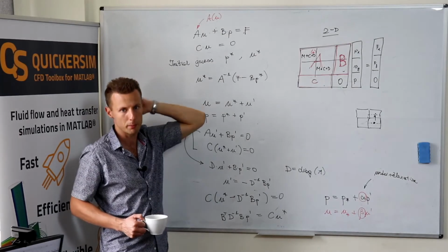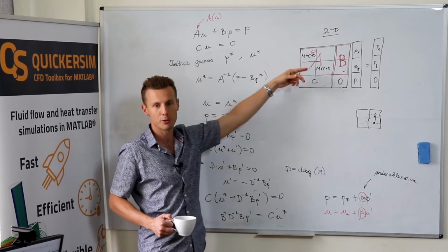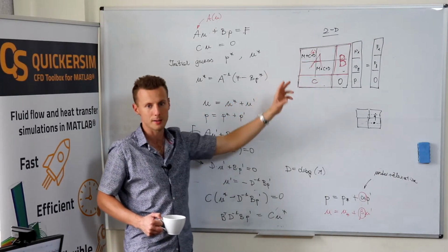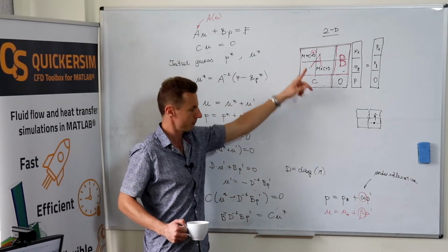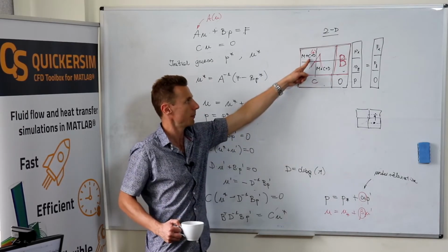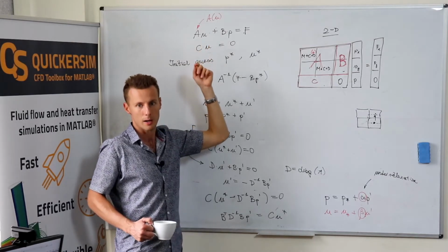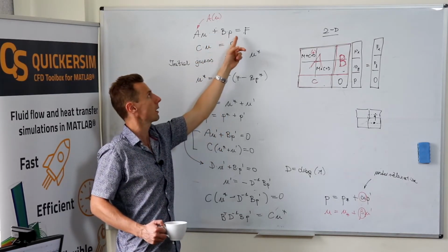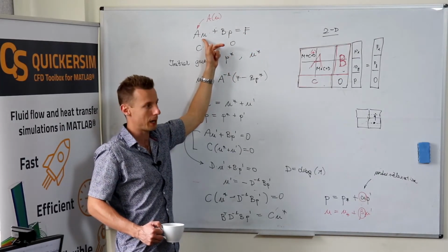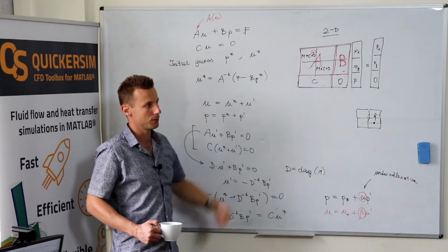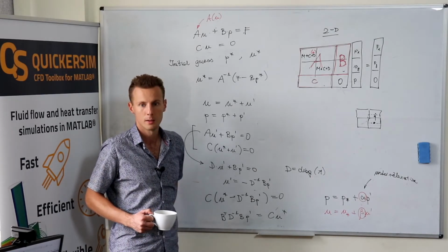Okay. And you need to remember that, again, the discussion of the nonlinear convective term applies here. So once you've solved the linear system of equations, you need to update the velocity and you need to update it in the convective term. So your A matrix will change. And certainly Fluent does calculate the residuals once the matrices are already updated and given, and you have the current pressure and velocity field. Okay.